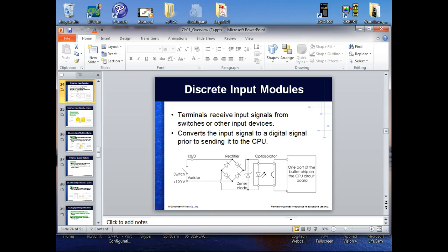This is on your TV. What they do on the PLC, if you pop this open, you see a little square thing. You've got six pins on it. It's usually yellow. Most of them are yellow that I've seen. So you see it as an integrated circuit, when actually it's an optical isolator. So if you did something out here and you mess things up, you might lose one of your input ports. But normally, if you use all your input ports, you've got a big problem anyway.